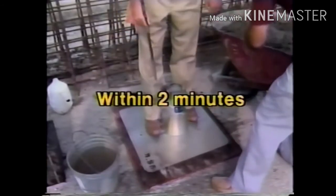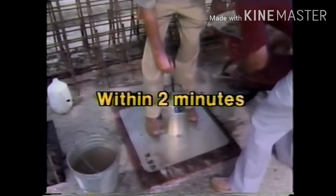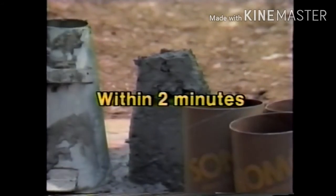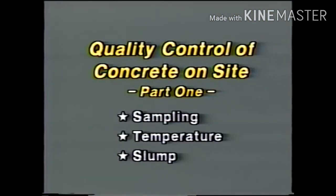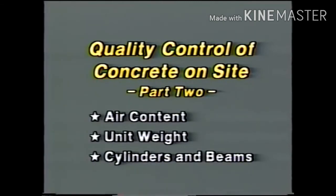The entire slump test must be accomplished within 2 minutes, as measured between the adding of the first layer and the measuring of the slump. And that's sampling, temperature, and slump. And the end of Part 1. In Part 2, we'll cover air content, unit weight, and the making of cylinders and beams.